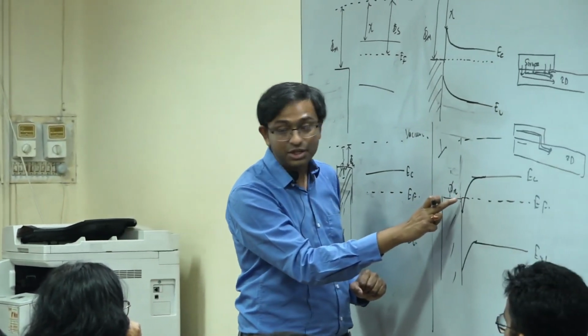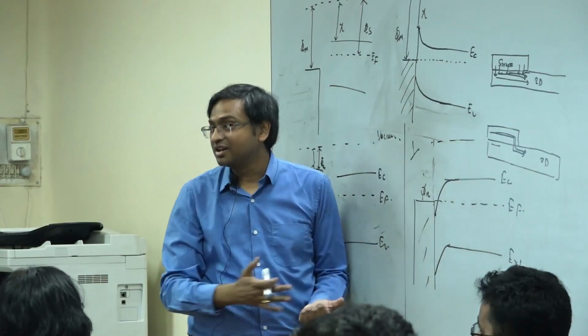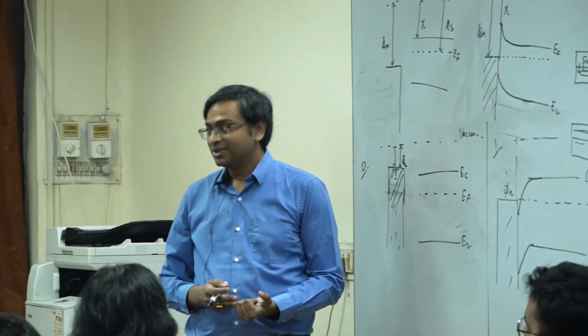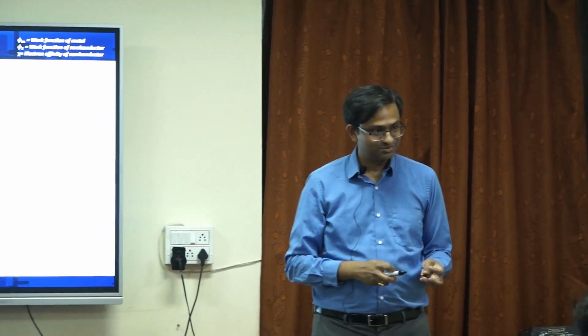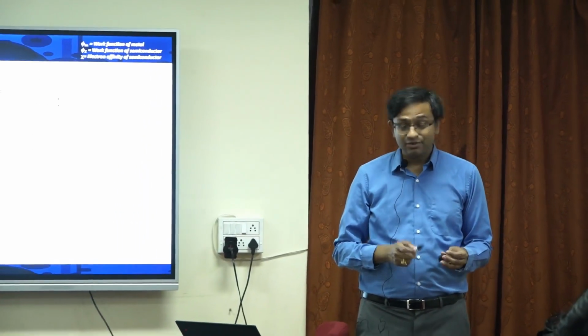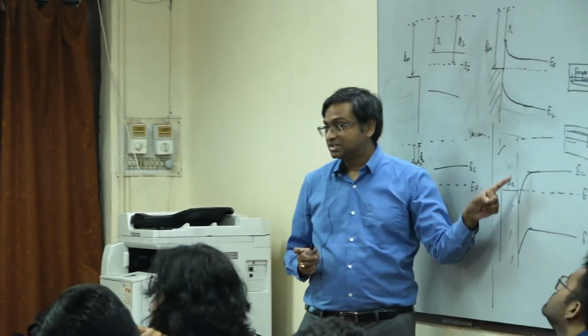That's a very critical thing, because when your Fermi level moves into the conduction band, what does it mean about the semiconductor? It is degenerately doped, correct? And that is why it becomes an ohmic contact. Make sense? Bending will be not only more, but you see there is also a crossover. It's just not the bending.